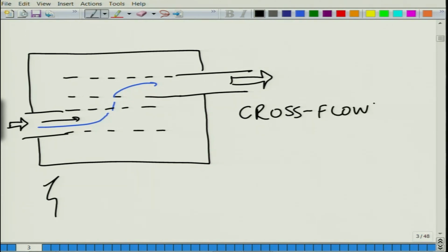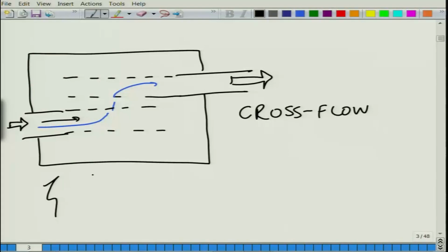I will also obviously discuss this at a later time when I discuss the relevant maths behind it. But one thing about cross flow elements is that they have slightly better attenuation performance than simple grazing flow muffler configurations, but at the expense of higher back pressure. So, that is one thing you need to keep in mind. It is not like it can be used everywhere just because the attenuation performance is good. There are other constraints we also need to be mindful of.